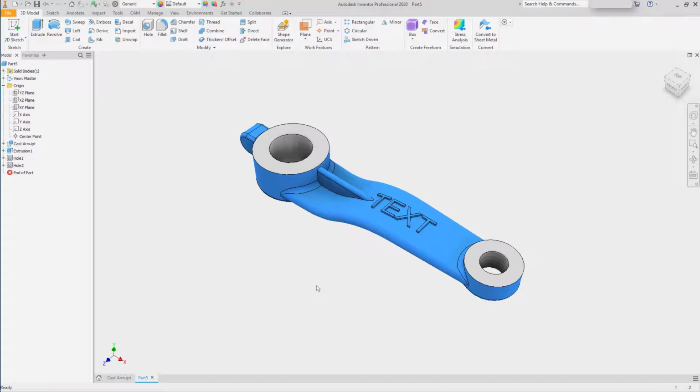Of course, the issue with castings and the value of using derived components for castings and for other workflows where you have a model, a series of parameters or sketches that can be used as a starting point for a new model, but you want to maintain a connection to the original, that's what Derive is best at.